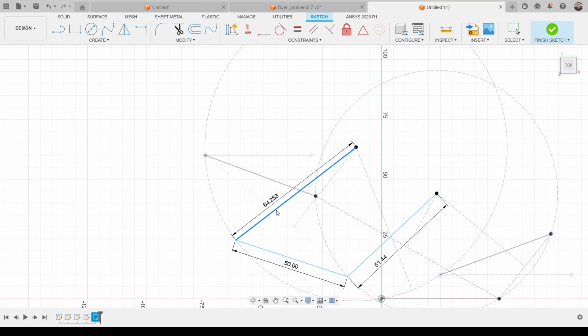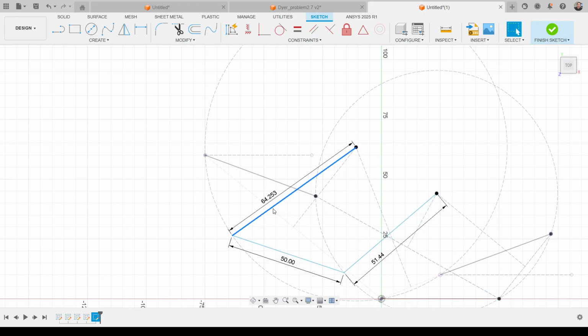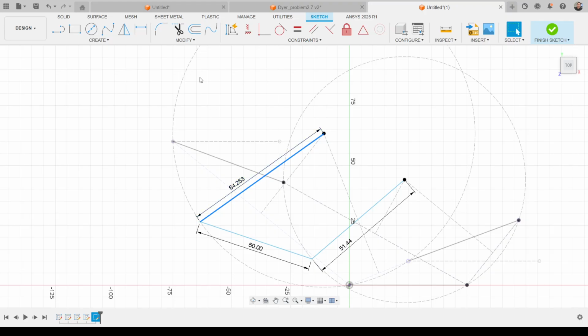So now we have defined the 4-bar mechanism which meets the requirements obtained from this problem. And maybe you are wondering, what is the length of the missing link, which is link 1? With that one you could proceed to check if this mechanism meets the Grashof criteria or not.